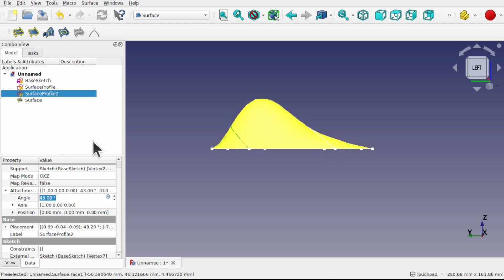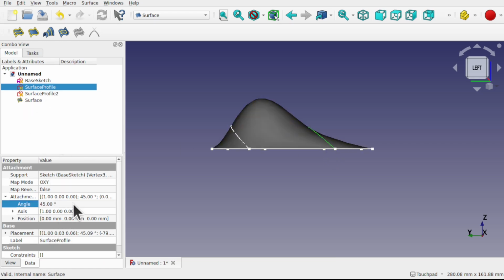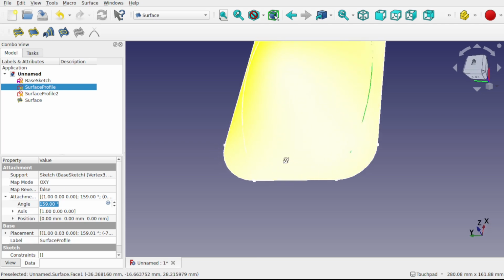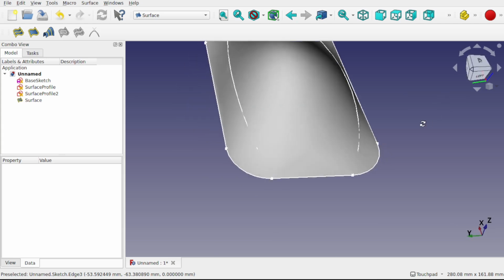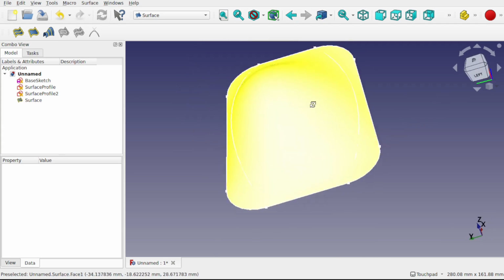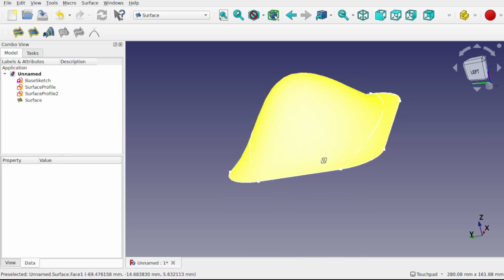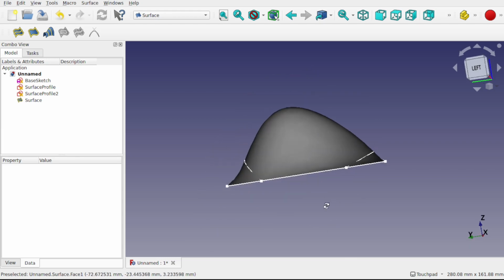If I move both of these arcs out of the way, so this one here, and bring this right the way around, so it's over in this direction, hit Control R, you can see what's happening. So we're getting this arc between both these points. So we can make this curvature in, say, like a panel or something like that. The more arcs we add, let's say we added a center arc, then that will constrain the center of this surface.